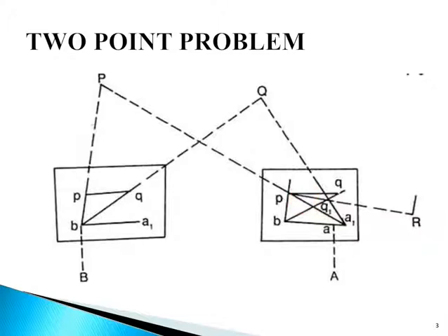So the alidade is placed along the line pq1, and a ranging rod at R is fixed at some distance from the table. Here you can see a ranging rod is fixed at some distance from the table. Then the alidade is placed along the line pq, small p and small q, and the table is turned to bisect R, capital R. At this position, the table is said to be perfectly oriented. So orientation is done.